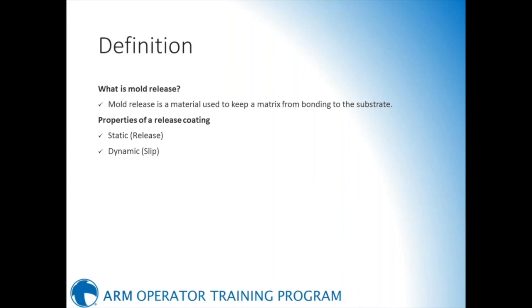So you can kind of think of it like this. When it's pulling your polyethylene just straight off the surface, that's static or just release. If you have a threaded connector, a neck, or a leg or something like that, which is tight to get out of the mold, that's where you need slip and a release agent to kind of help that material out.